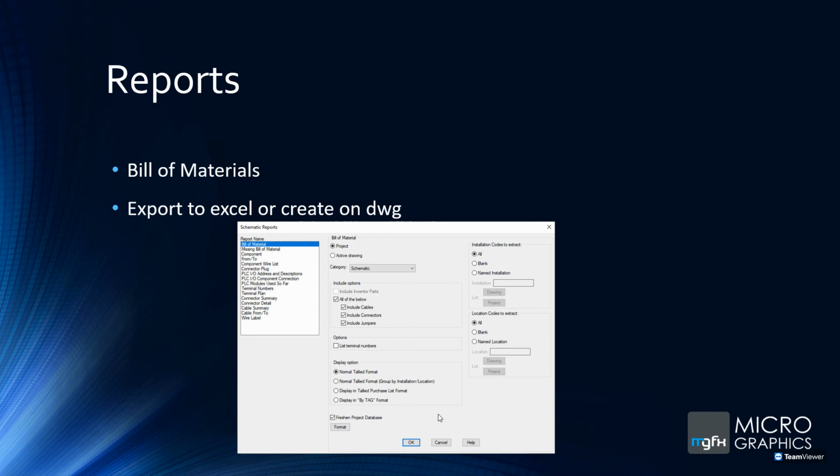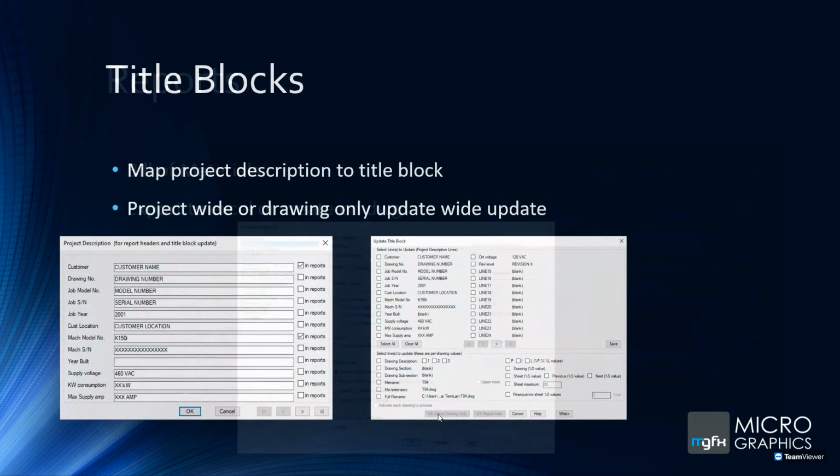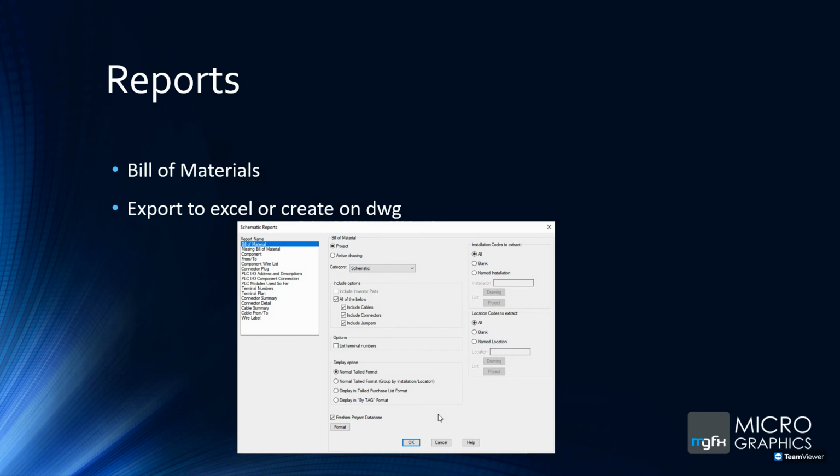And for all this stuff, the reports, the title blocks, creating electrical panels and creating your electrical schematics, everything in normal AutoCAD is manual. So you'll see there that everything you'd have to do, you have to change. There's no automation in it. I know a lot of the guys out there are doing electrical drawings in AutoCAD LT. Even there, you can't automate the table creation of a semi-pseudo bill of materials with a data extraction. So if you're using AutoCAD, like the full AutoCAD, and you have the AutoCAD Electrical toolset, sorry, my apologies, then take a look at it, and you can save yourself a ton of time.